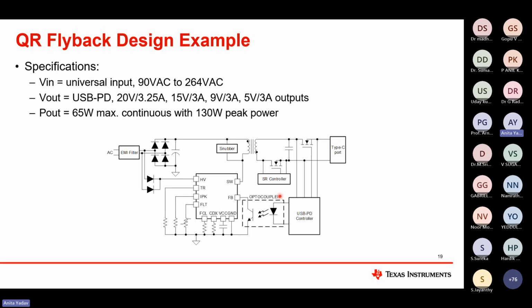There are multiple things to be considered while doing component selections. We need to check the components with respect to their rating. That is the first thing. Then, if they are preferable, like series-wise, if I talk about the resistor selections, there are multiple standards like 0603 package, 0402 package, 1206 package, 0805 resistor package. So what happens if we don't plan it properly, then it will not go well.